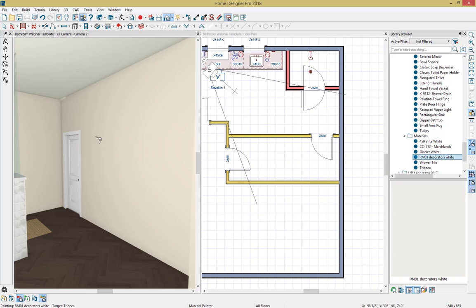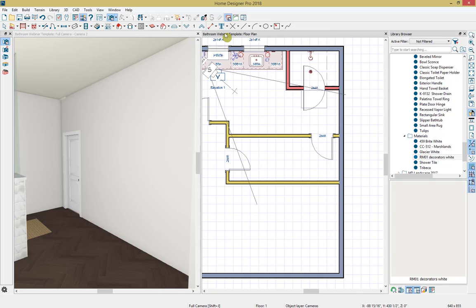And so I'll select the room mode and I'll paint this on to make all of our walls white. Now that I've done this, I'll select my spacebar, and I would like to get into my floor plan view, and I'll use something called the break wall tool to break walls. The point of the break wall tool is to separate walls so that you're able to edit and modify them as needed.